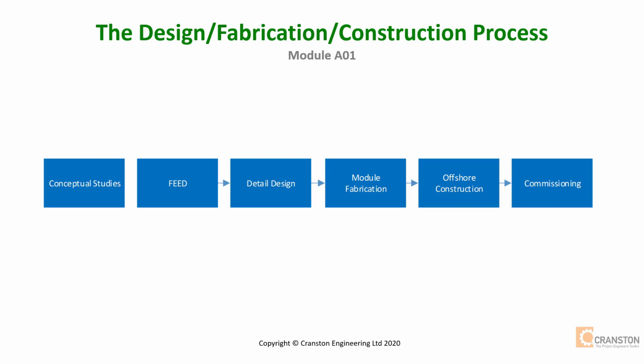Accommodation projects follow the same design process as other offshore projects. As in other projects, it's important that adequate time and effort is spent on the conceptual design and FEED to ensure that the project's fully scoped, as changes in detailed design or manufacture will be orders of magnitude more expensive. We start with conceptual studies, move into FEED, detailed design, module fabrication, offshore construction, finally commissioning and handover.